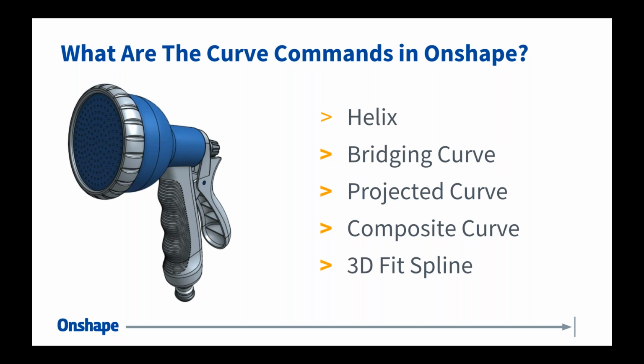And then a 3D Fit Spline. That also falls in that category of a curve, and that's the last thing we're going to discuss here today. The thing that's unique about 3D Fit Spline is you essentially tell it the points that you want your spline to pass through, and you can define how its start and end direction is controlled. The neat thing about that is you can align it with surrounding edges. Again, a lot of these commands are really about creating smooth curvature, smooth transitions between shapes, and 3D Fit Spline is no exception. It has the ability to match those surrounding edges.